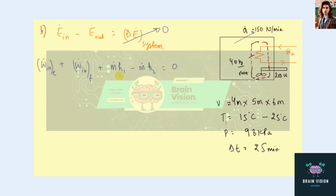Now from here we can take these two terms towards the right side, so we can write the work input by the electric heater plus the work input by the fan, and it would be equal to m dot h2 minus m dot h1. Now this would be equal to m dot Cp (T2 minus T1),